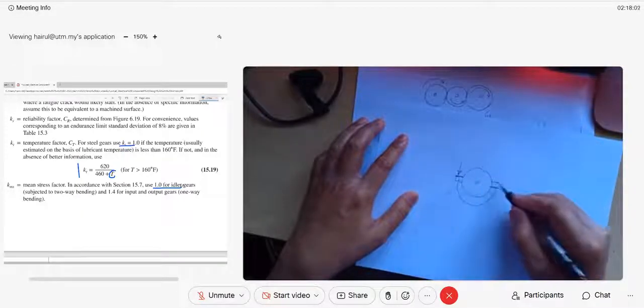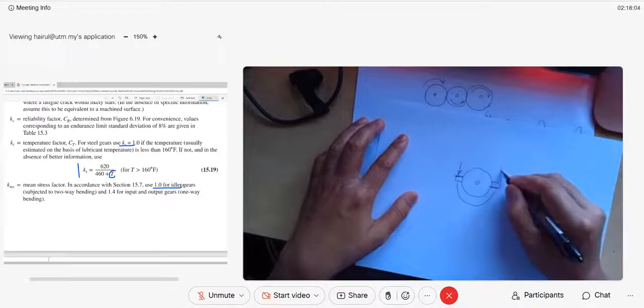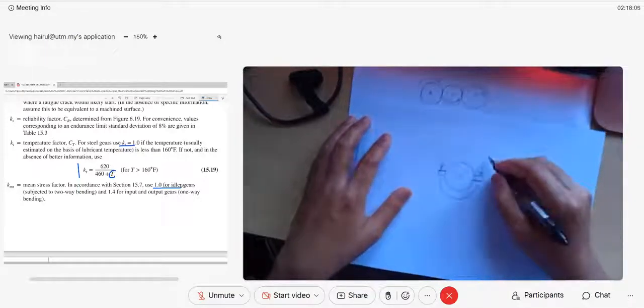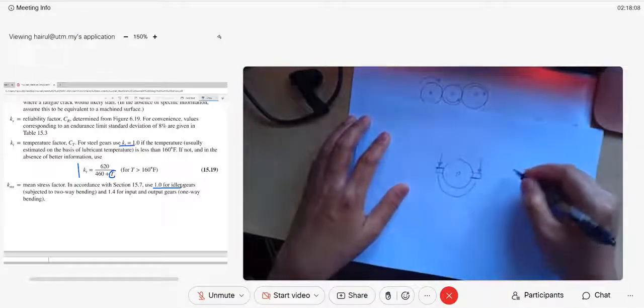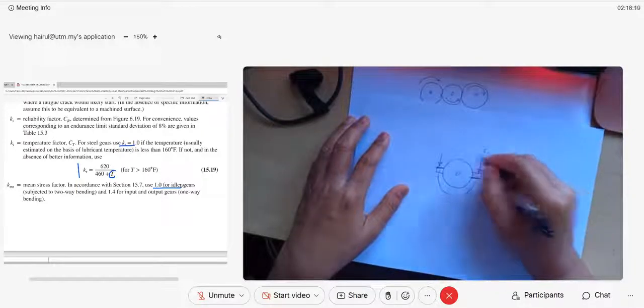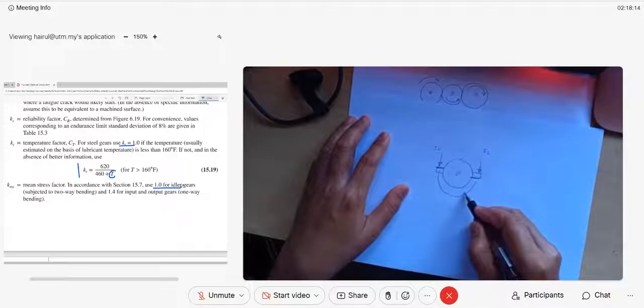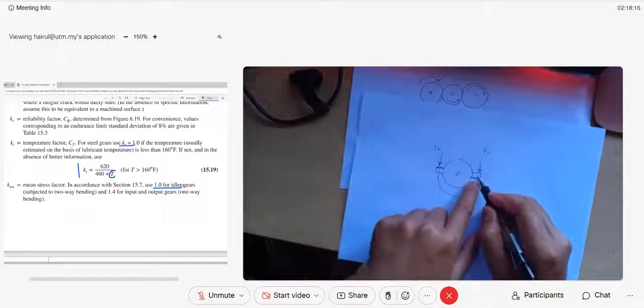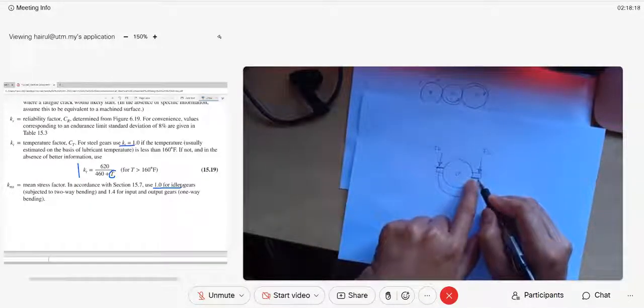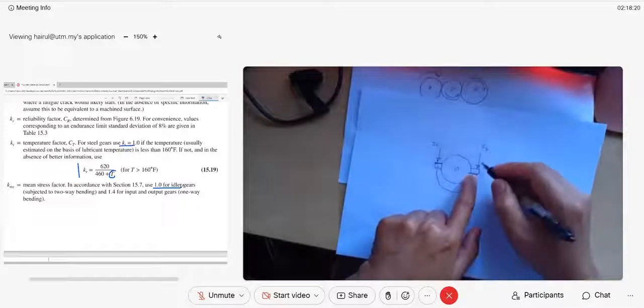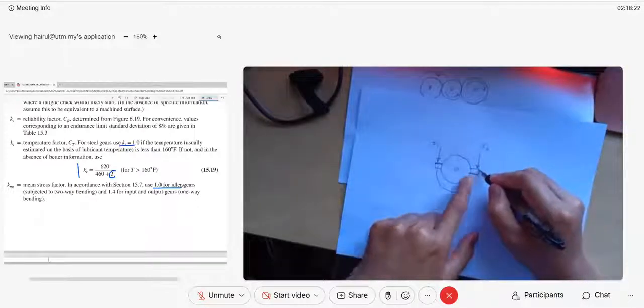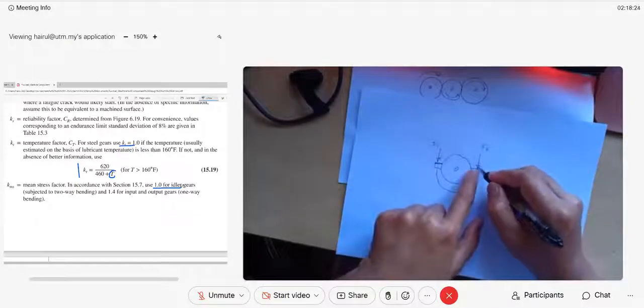This bottom surface here becomes top, but this one will receive impact from the output gear. So both of the idler teeth, we have F tangent at this. F tangent is at the top surface. When it goes in this direction, until the top surface becomes bottom, the top surface does not have impact from the tooth of the output gear, but at the other surface, the bottom here becomes top. The other surface has the impact.